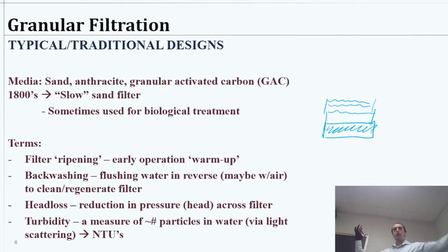So essentially, if we caught a particle early on in the filter and it just gets stuck pretty early, maybe hours and hours later, it will have worked its way through these little grains. Every now and then the water kind of pushes it a little further. Maybe something shifts a little. Eventually that stuff will start coming out, right? So eventually we would have breakthrough of the particles, which would be very bad.